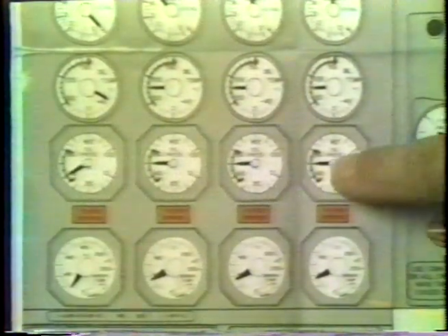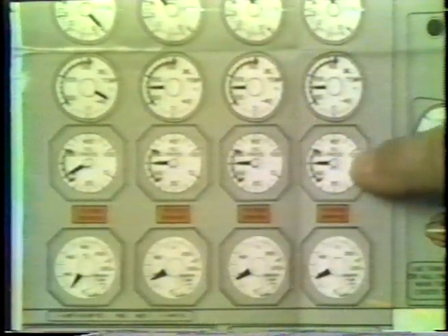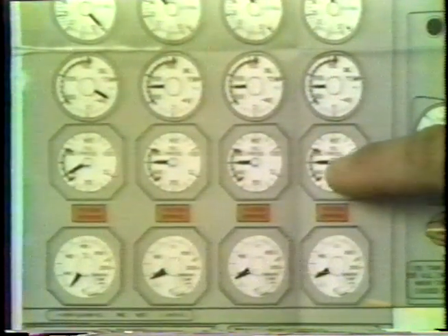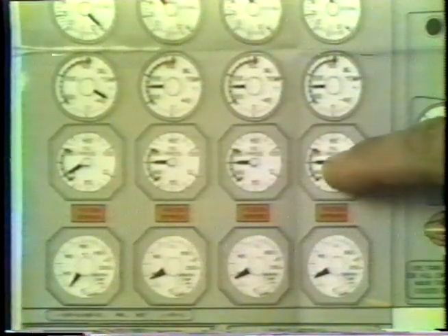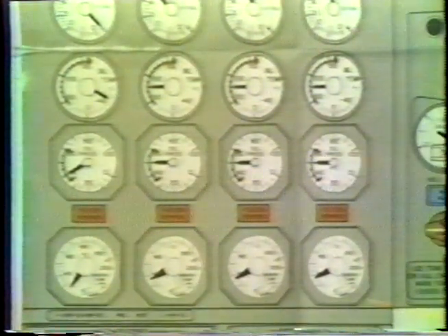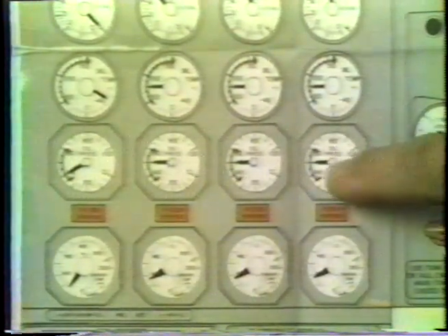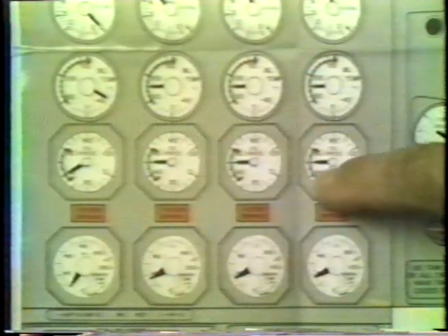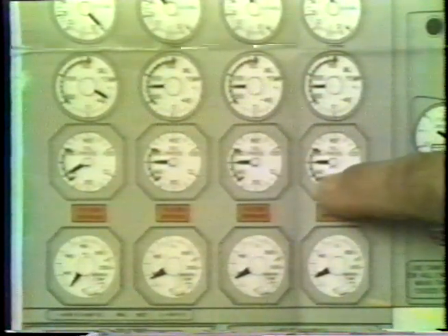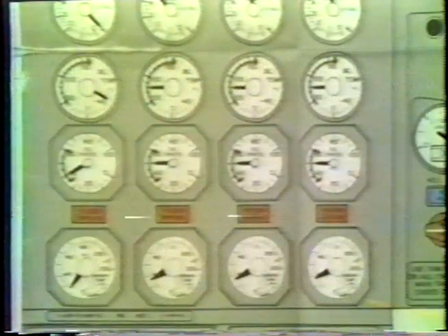Oil pressure. Oil pressure is monitored during engine start and should be in the green band by the time the engine reaches idle. It is permissible to operate for a period of time the engine below the green band in the caution band for ground operation.